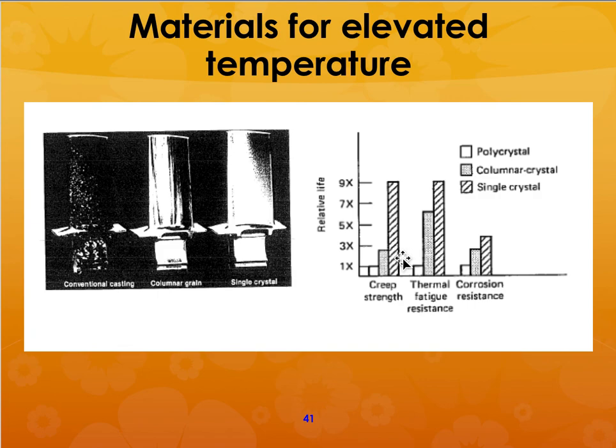If you have single crystal alloys, you can get 9 times the lifetime for creep strength, 9 times the lifetime for thermal fatigue resistance, and corrosion resistance is also much higher than that of polycrystalline material. So reduce the number of grains, make it a coarse grained component. It will increase the lifetime of your component.